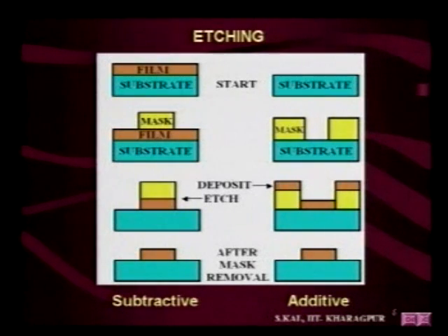Okay. So the aqua regia is a very strong etchant solution. If you use the masking layer as a photoresist or other metal film, the aqua regia will react with those photoresist and other masking film. So you cannot pattern gold by etching with aqua regia. The whole gold as well as the masking layer will be dissolved by the aqua regia solution.